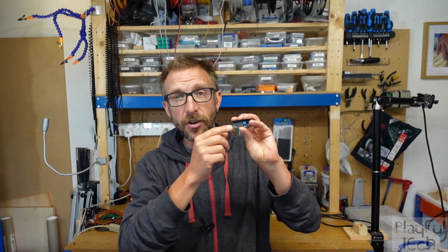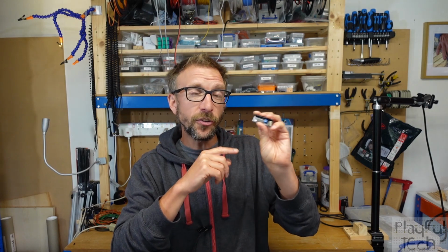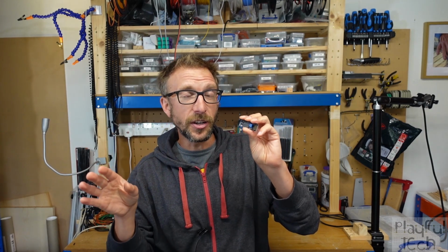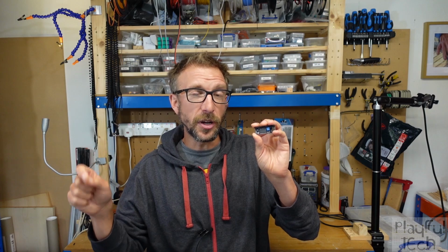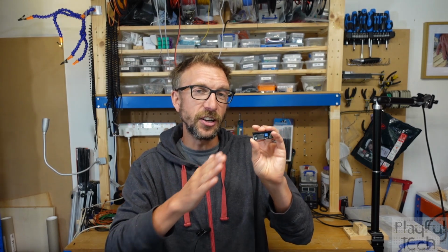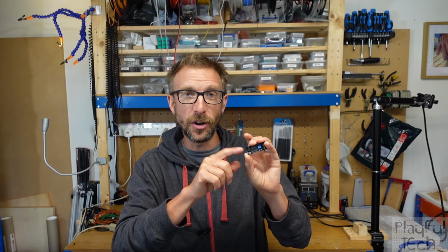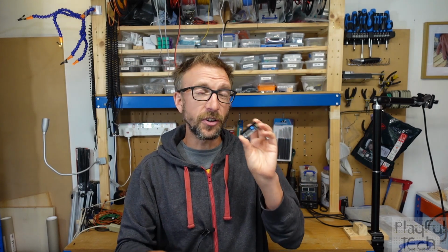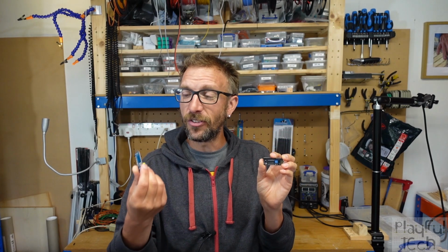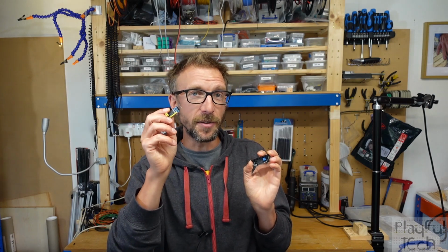It too comes with an I2C interface, but it also has a variant that uses an SPI interface from the controller to the chip instead of I2C. Now this uses up one more pin of the Arduino or the controller, but in return it is significantly faster. It's a 1.7 megahertz connection from the processor to the chip rather than the 400 kilohertz of the PCF8574 I2C interface. But it is also significantly more expensive, whereas these really are very cheap and easy to obtain.